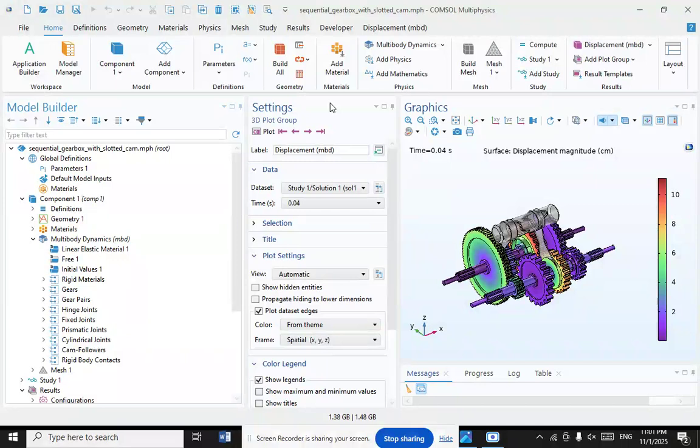In this position, the dog clutch is prevented from engaging. Once the speeds are synchronized, friction on the blocker ring is relieved and the blocker ring twists slightly, bringing into alignment certain grooves or notches that allow the dog clutch to fall into engagement.